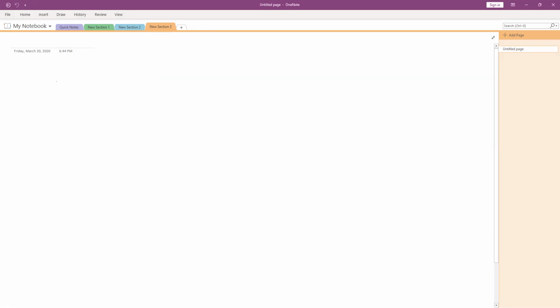So what we had was a voltage source. And this was Vs, and I believe it was 12 volts. And then we had that connected in series with a resistor, and that resistor had a value of 1 kilo ohm. And that was connected to our LED. And that's our schematic symbol right there for a diode. And then when I add these two arrows, that means it's an LED. And what we used was a red LED.